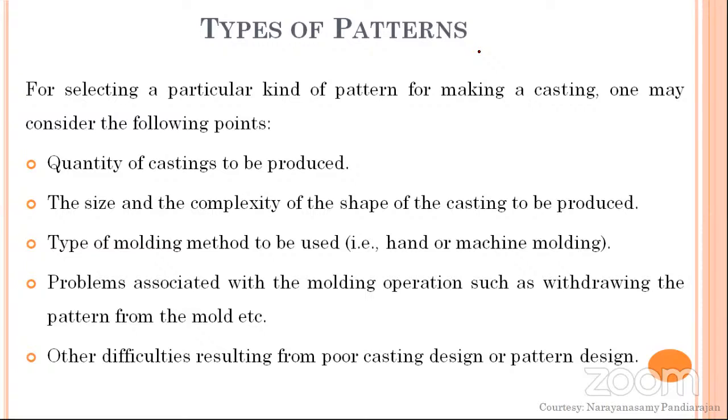If you keep a rectangular block vertically, the space occupied is less, and if you keep it horizontally, the space occupied is more. So the placement of your pattern in the mold is also one of the factors in deciding which type of pattern to select.